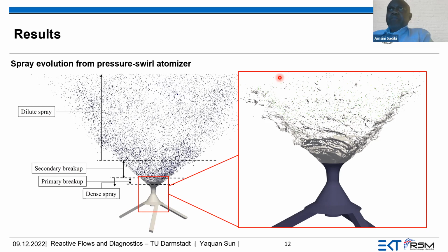Not really a big modification, but you only have to introduce a cavitation model, like in the work I have shown you. There is also a cavitation model, but I didn't show you the results. Using a cavitation model, you can capture this in a correct way. So VOF with the cavitation model should be able to do that, right? Yes.